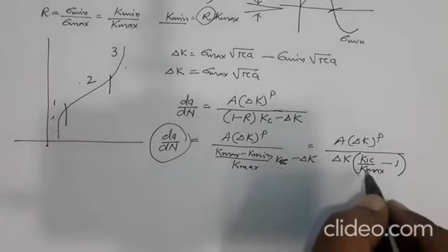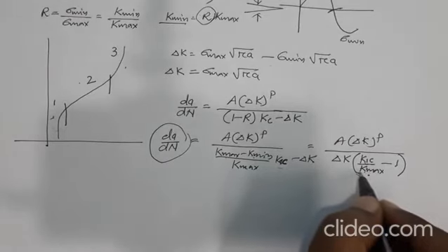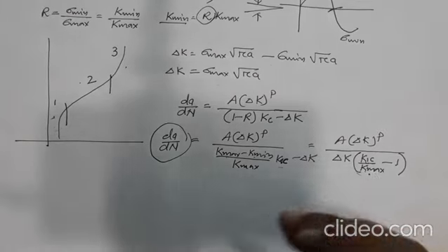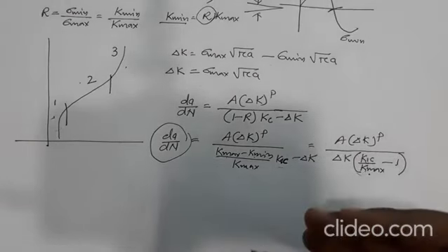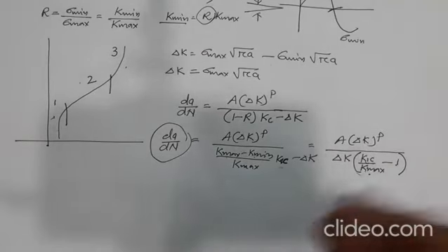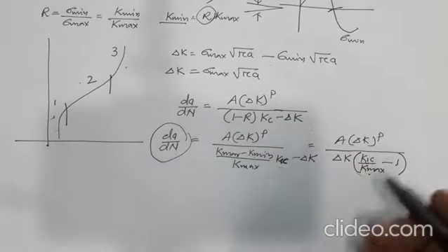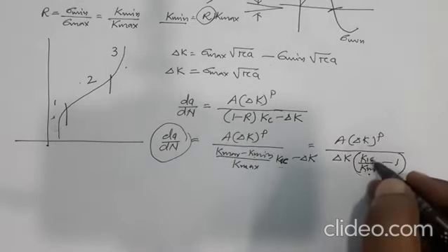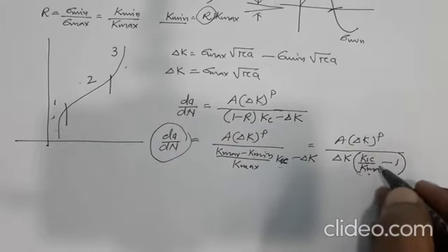So you see, when this value will always be greater than 1, right, because K max at most can reach the fracture toughness value. You cannot go beyond that, because once you reach K1C, it is going to propagate anyways in monotonic loading, and we are talking about cyclic loading. So K max usually is less than K1C, and this factor is always greater than 1, right.